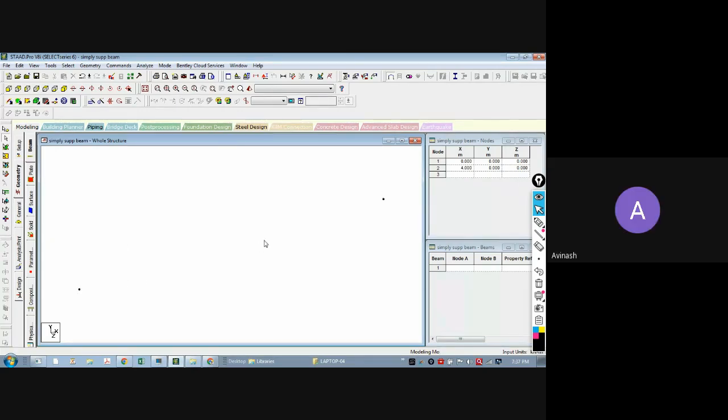Now as we are not having any z coordinate here because our structure is not 3D, so you can only see the XY plane. Now you can see 3D plane here in the white screen. If you want to see only front view, X and Y coordinate, you can click here, yellow color, view from plus Z. Now here you can see Z is perpendicular to the screen and X is to the right side, Y is upward.